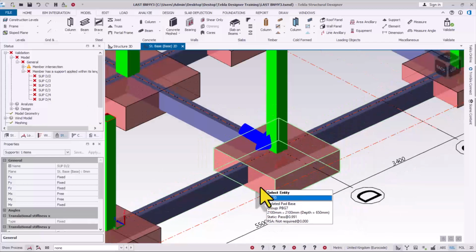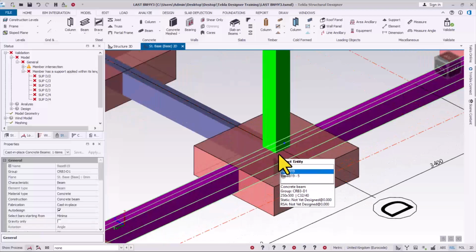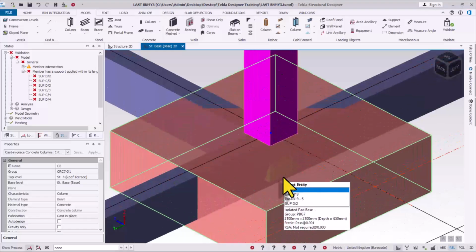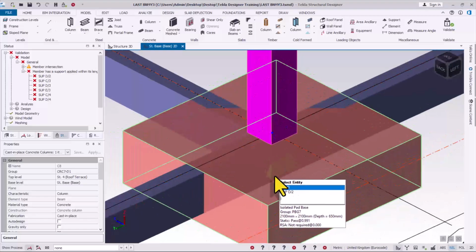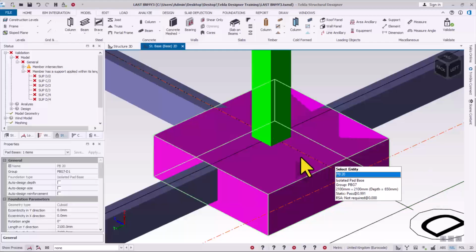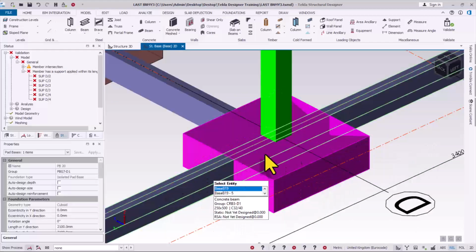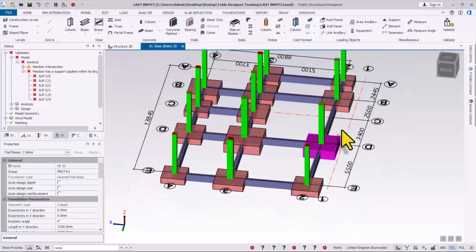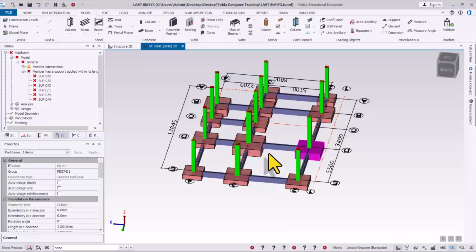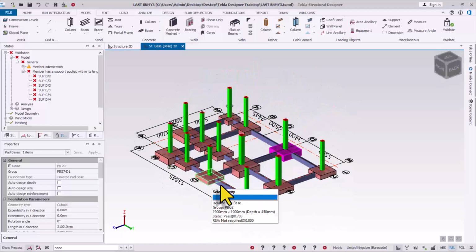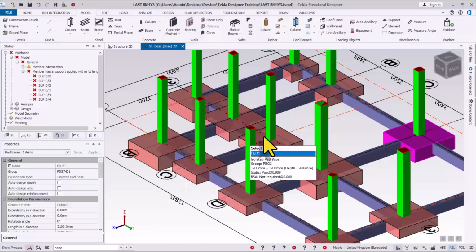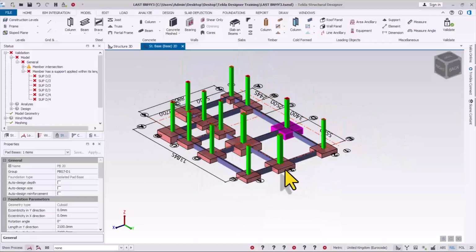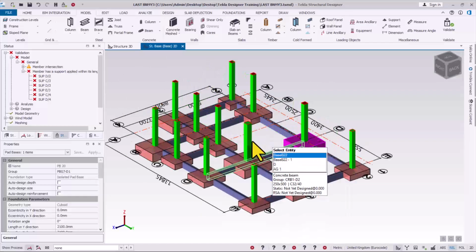So what does this mean? I'm having a beam cutting across the bottom constraint of this reinforced concrete column, acting as a support to the column, while the column still has an additional support, which is the normal support right there. So these two supports are clashing. So that is why it is an error. How do we correct this? We need to remodel this foundation beam to correct it. Okay, so this is the first challenge you always have while you are trying to model and design foundation beam in Tekla Structural Designer. So let us correct this.